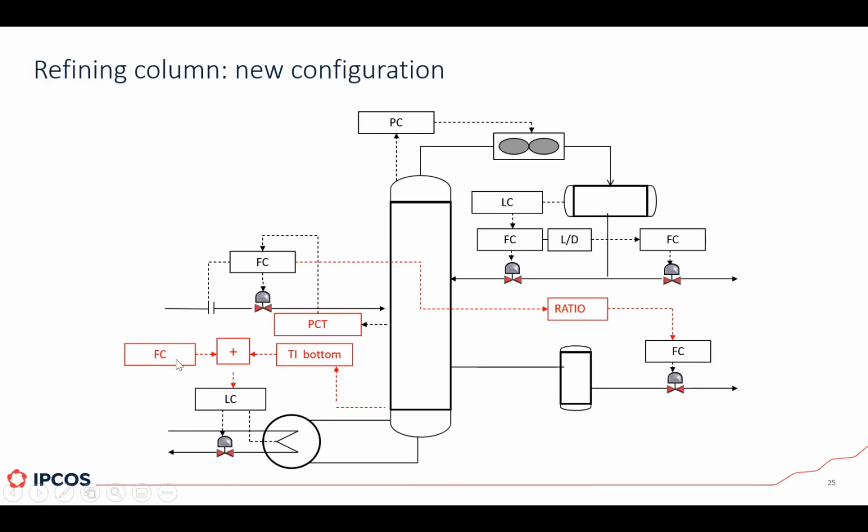In fact, with the duty, at least before we implemented advanced process control here, just on the regulatory control, this allowed them to have a clearer handle on how to change the production. Before, if you remember, the feed flow was attached to that temperature controller, so it was not that clear for them how to increase or decrease production. But here, this gives you the handle that you need.